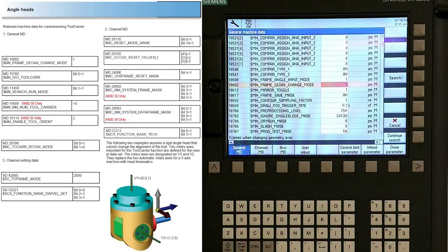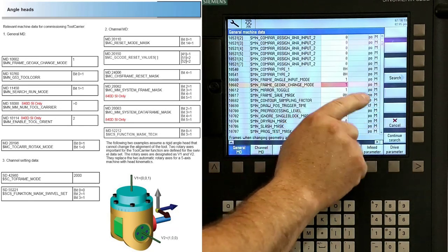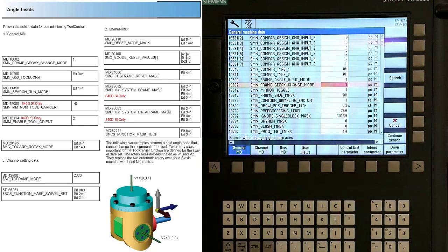Now I'm going to start typing in the parameters as recommended by our reference, which is what you have in front of your screen. It's worth noting what is stated just to the right of the parameter. You see how there's a PO just to the right of the parameter? That designates that this parameter is a power-up parameter. So if I was to change this parameter right now to make it active, I would have to reboot the system.